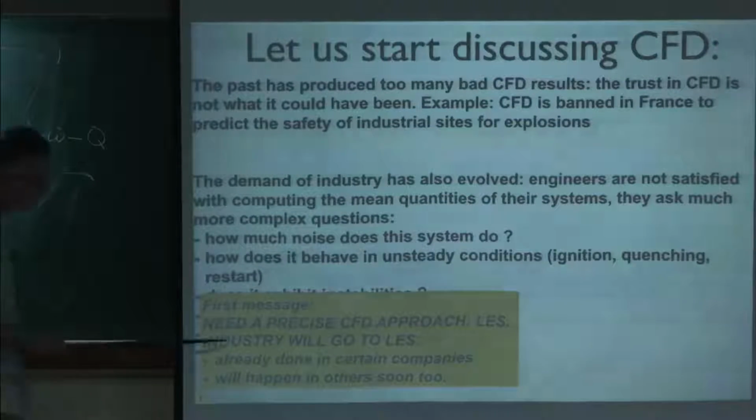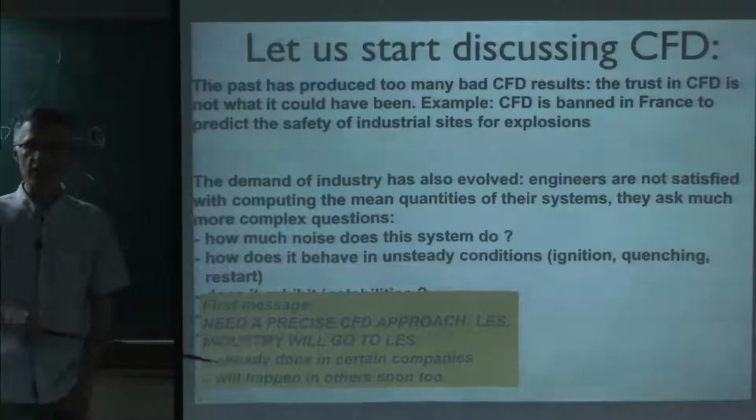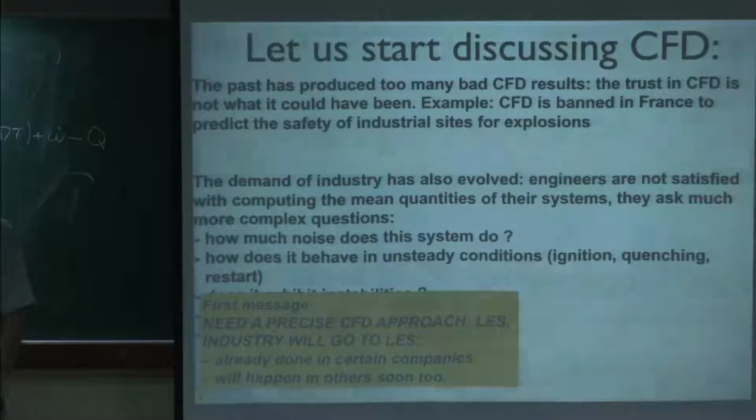It's already done in certain companies, not only in the lab. There are companies in France like Turbomeca doing helicopters. Actually, it's the world leader in the field of helicopter engines. In the combustion department, they have completely pushed out RANS. No one does any RANS anymore. They all do LES. But it took 10 years, during which we've been continuously comparing RANS and LES for every new engine, until they found out that systematically they could trust LES and they could not trust RANS.